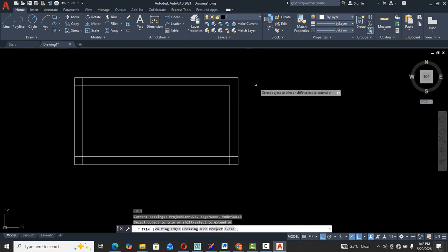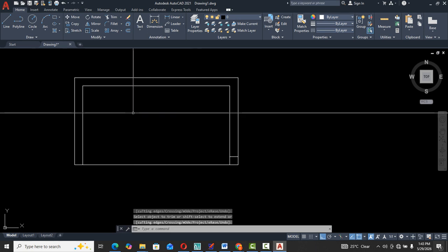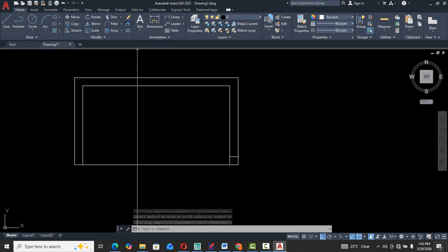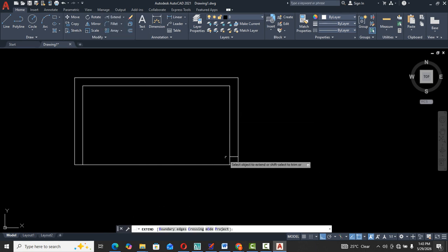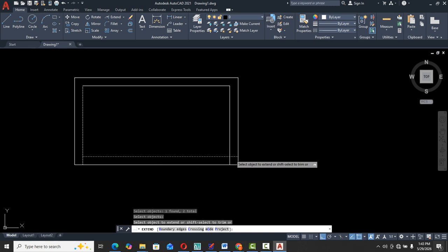So we can also go to create. I can create a block definition by selecting objects, specifying an insertion point and giving it a name. I can edit the block layer and all that. I can also edit attributes, but these are beyond the scope of this class. Then we have match properties. We can also match properties. Then we have our layers, and we can give each of our layers colors.